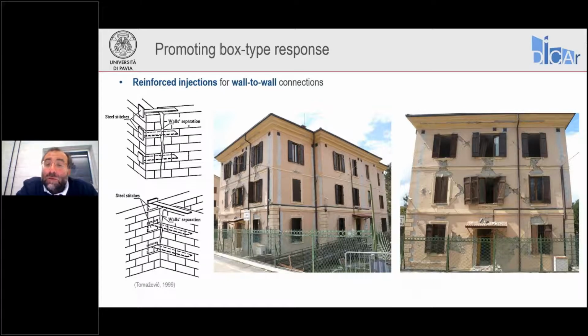The fact that the building was heavily damaged in its plane meant that this building had to be torn down after the earthquake. However, no one died in there, it didn't collapse, and it survived the earthquake, even though heavily damaged. All the damage is in plane.